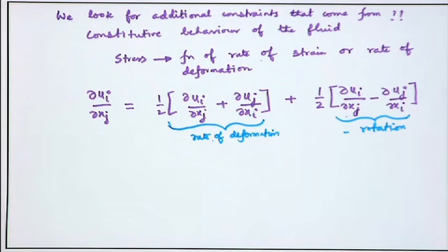I have got one answer which is viscosity. This is not correct, because viscosity will give rise to stress when the fluid is under deformation or motion. The other answer is weight, that is also not correct. Of course it may be related to weight, no doubt about it, but it is a fundamental fluid property which is not weight.